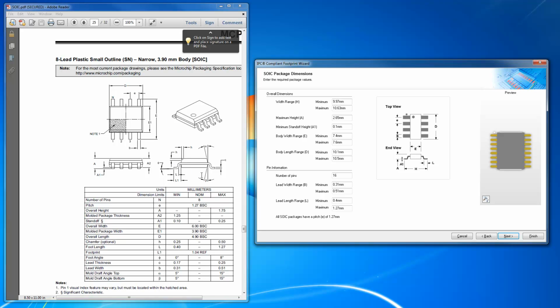They're showing it over here, and they're calling it E. So here you can see how they're calling it H over here, and over here it looks like H, but actually they're showing it as a part of E. So when we take a look at E and we follow it down over here, they're calling it 6 BCS. Okay, if you actually look at it, it says 6.00 BSC, so I need to correct myself from earlier. Well, what does BSC mean?